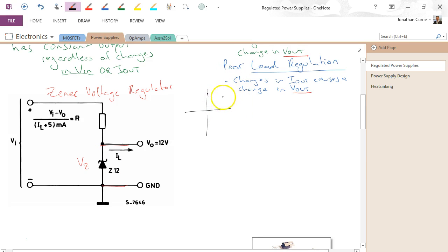Alright, so remember, we have a look with the Zener diode, that when we operate it in forward bias we get the normal diode. So sorry, that's current, that's voltage, and this is forward bias over here. Get the normal diode response, but when we operate it in the reverse bias we also get this knee voltage here, or Zener voltage, where it will actually keep that voltage and allow current to flow through it.